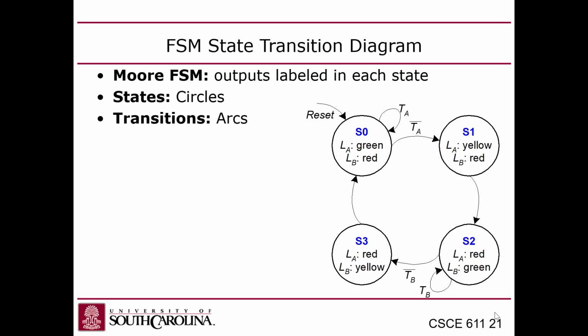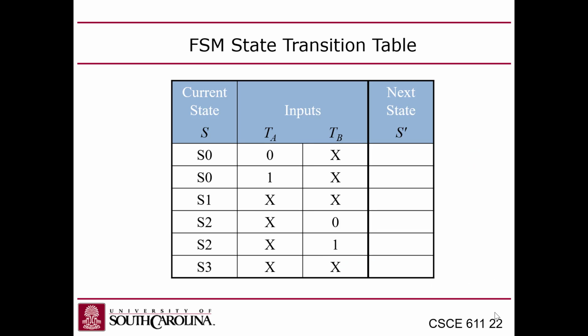And actually, maybe they should have put that in there, because to stop that pinwheel type effect, you could stay in this state, even if there's no traffic on academic, until there is traffic on Bravado before you jump to S1, right? In which case you could just say TA equals 0 and TB equals 1, right? So you can add an additional condition here to not go to S1 unless you have some traffic on the other street. But they didn't show that, so the TB is a don't care.